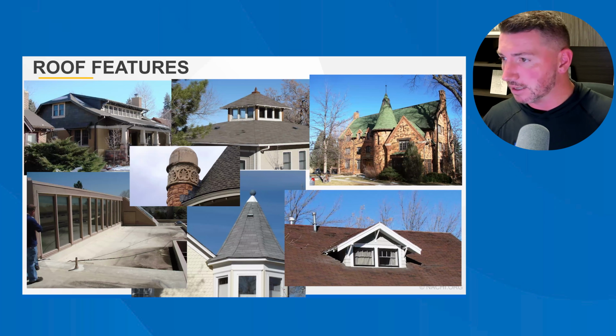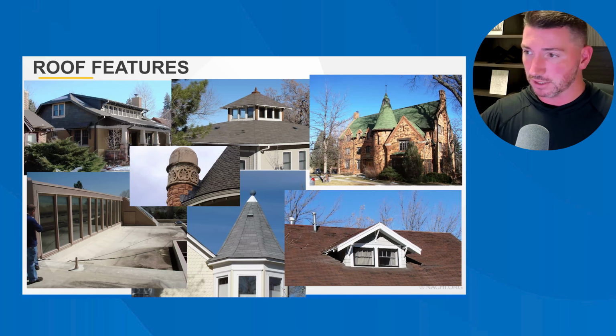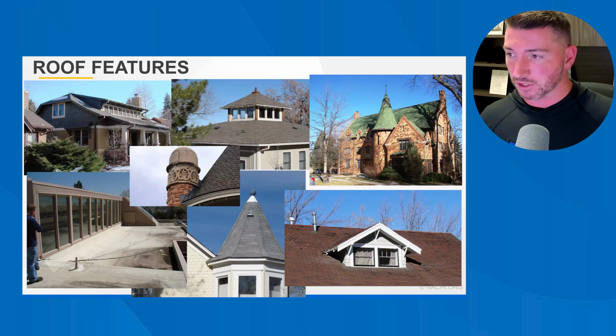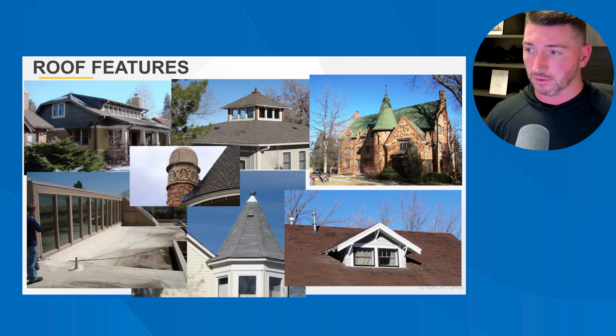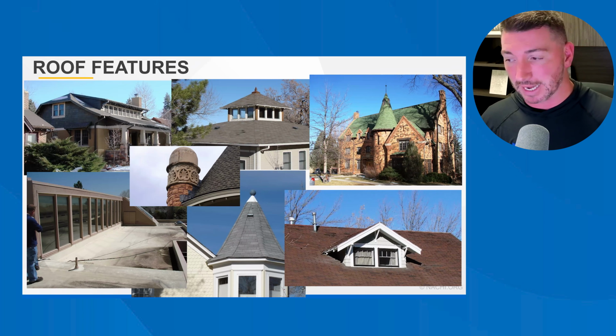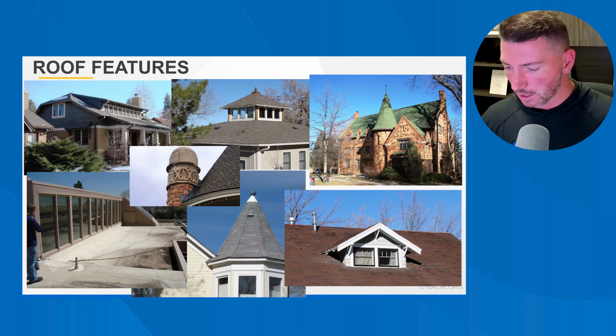So as you can see, the top left photo, the clerestory windows do not have adequate clearance from the surface of the roof up to the sill of the window. It's kind of sitting right down on the window, and doesn't seem like any of these really have adequate clearance, maybe except that one with the TPO roof. That's a pretty good little drop down from the sill.